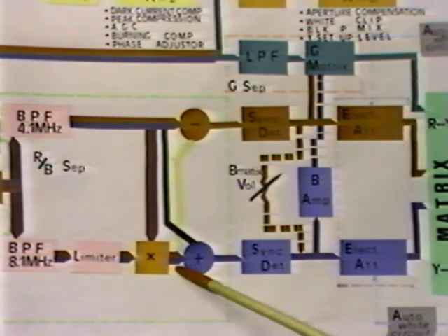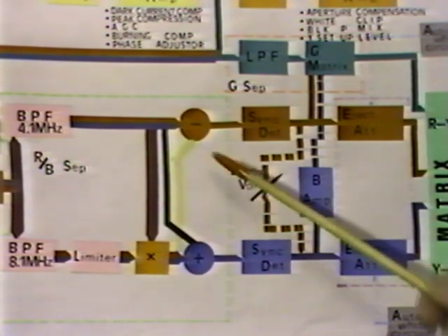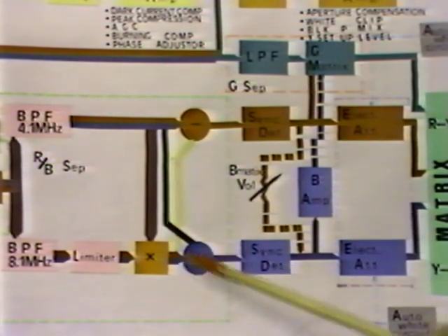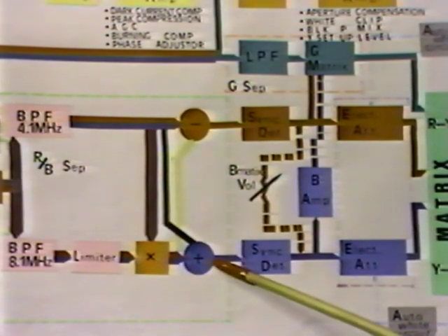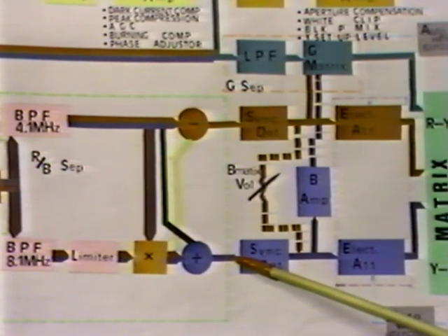This way, the second higher harmonic is converted to 4.1 MHz. This new 4.1 MHz wave makes the B signal amplitude modulation wave by adding the original 4.1 MHz fundamental, and the R signal AM wave by subtracting the original fundamental wave.